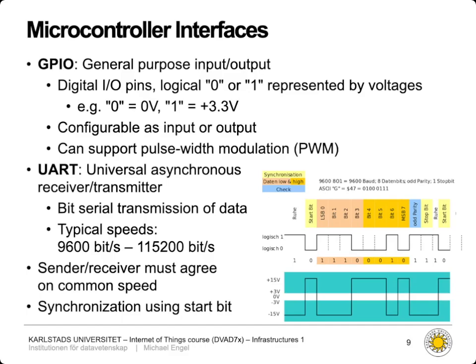And over that time, even if you have different clock sources, which are not exactly on the same frequency, but might differ by like 0.5% or so, you synchronize every like 10 bits you send. So essentially, the probability is very low to run out of sync during these 10 bits. And then when you send the next byte, including start and stop bit, then you synchronize again. So that's why UART interfaces actually work as well as they do.